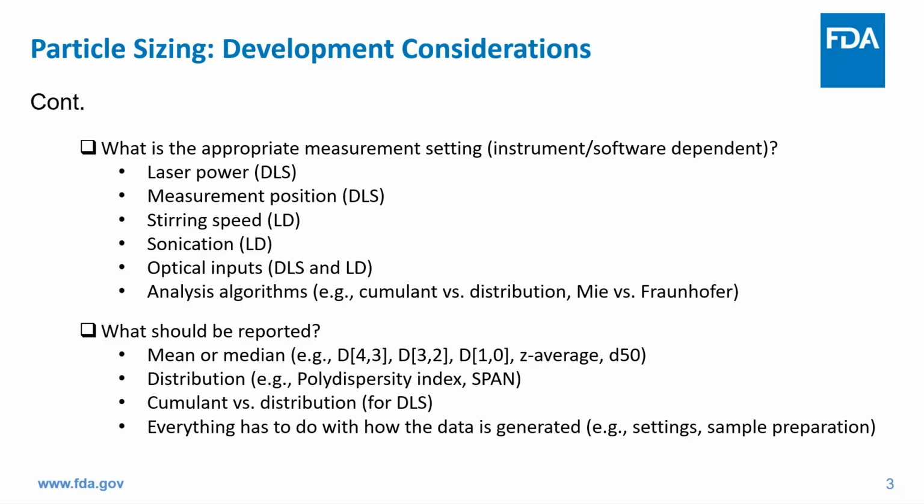Certainly, how fast you spin can help improve the dispersion, or you can apply sonication, which will help prevent the particles from agglomerating together and maintain separation. Remember the example Billy talked about yesterday, where over the repeatability measurements the size is getting larger and larger over the first 3 runs. That's typically because of agglomeration of the particles.